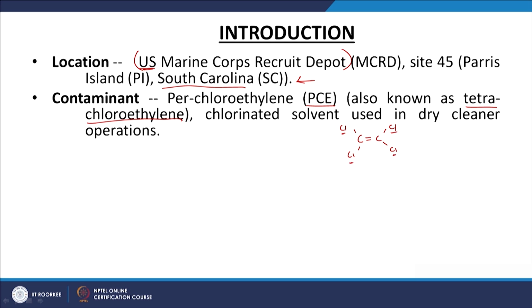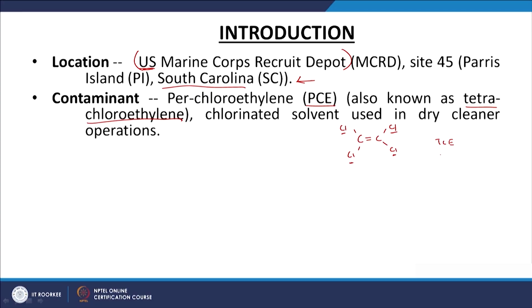And typically if there are reducing conditions, due to different pathways, either hydrogenolysis or cleavage of this particular Cl, let us say, right, you are going to have different pathways, and you can have TCE, DCE, vinyl chloride. Again, vinyl chloride is pretty toxic, DCE is also toxic. So, some of these byproducts which are formed when this particular PCE or tetrachloroethylene is degraded are also toxic. That is something I believe we looked at in the context of PRBs, or the permeable reactive barriers.